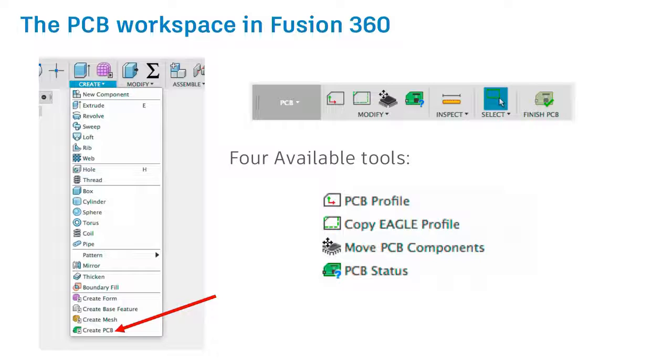We can edit the layout of 3D components, the packages from our Eagle libraries that are applied to the board, with the Move PCB components. And we can use the PCB status tool to see if any changes have been made to the board in Fusion since the last push to Eagle. We'll be demoing these tools throughout the presentation.